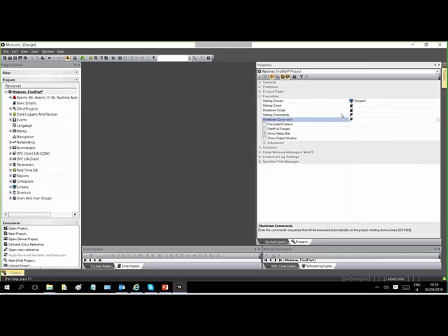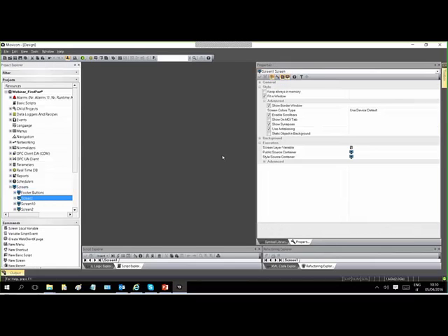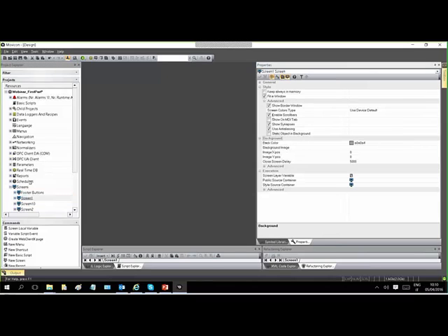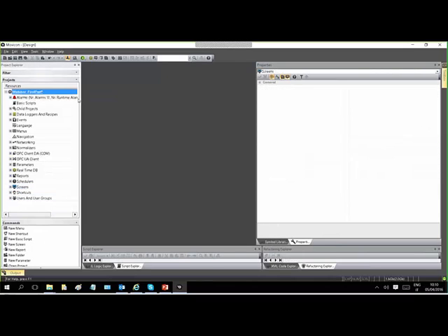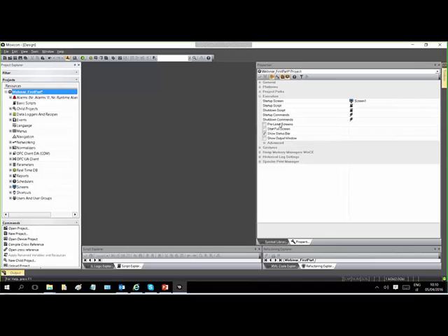Same, when the project shuts down, you can perform a command. Execution property, preload screens. It means that all the screens will be assigned as always in memory, will be loaded at the project startup. The project takes a little bit more at the startup. Then the screens are in memory, so you can switch between, for example, heavy screens in a faster way.